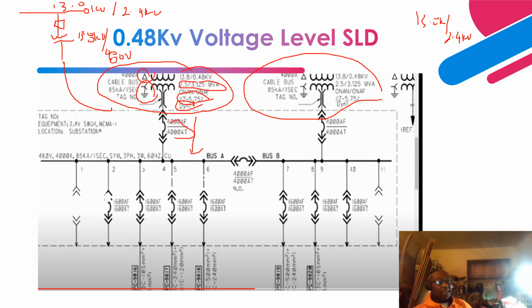These are solid state adjustable tripping devices, so they utilize long time pickup, long time delay, short time pickup, short time delay, then instantaneous pickup. So these are basically the solid state adjustable trip devices. That's what these trip plugs mean.